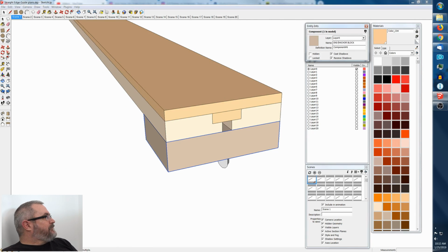And below that, or above that, is the... See, this is a part that I had trouble coming up with a name for, because it's not immediately obvious what the name of this part would be. So I think I eventually settled on load spreader, because that's basically what it does. It spreads the load of the head of the toilet bolt out further. It's just a piece of 1/4-inch plywood that does that.